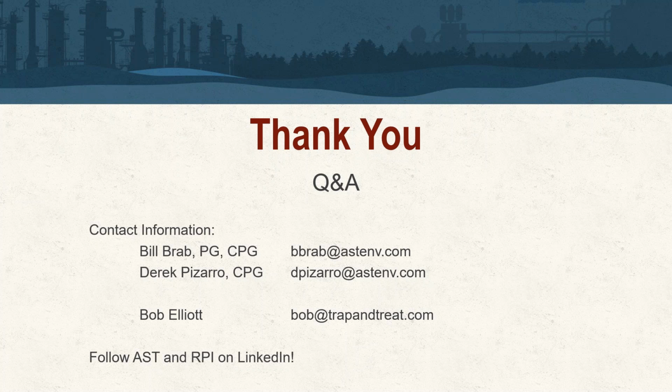First question here related to the process. Can your freshwater testing methodology be used in the subsurface to rehab wells that are heavily sedimented in? Yes. Let's take a step back. That's where the discussion about how this system was developed and why it was set up the way it was goes back to the domestic water well industry. That's how rehabilitation occurred, utilizing fresh water for cleaning out and rehabilitating these wells. And again, we're talking about open boreholes here specifically. I believe Ray may have had a capability of working with steel cased wells in the past, but specifically for remediation, we're looking at open borehole wells, not cased wells.